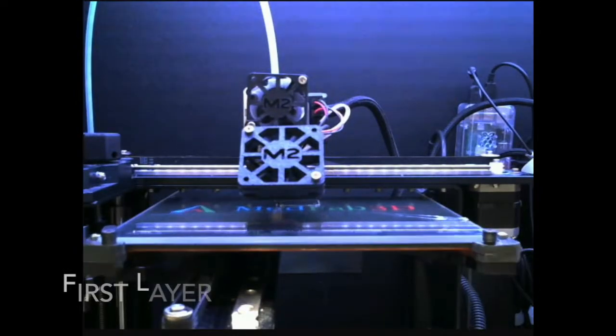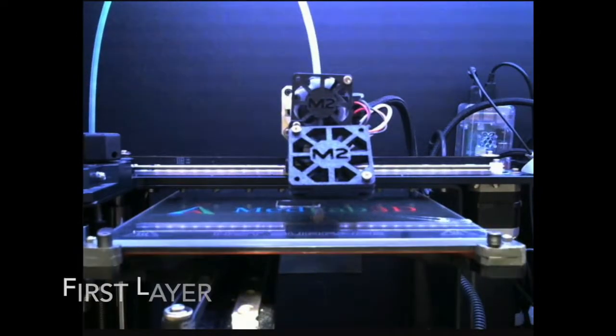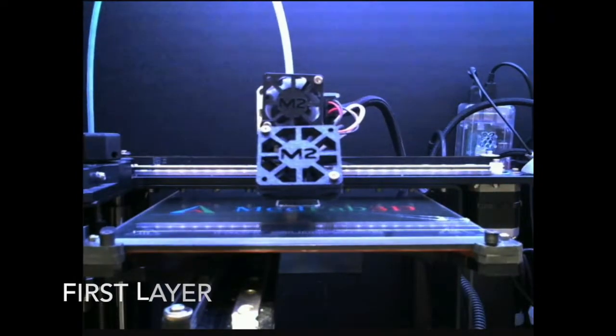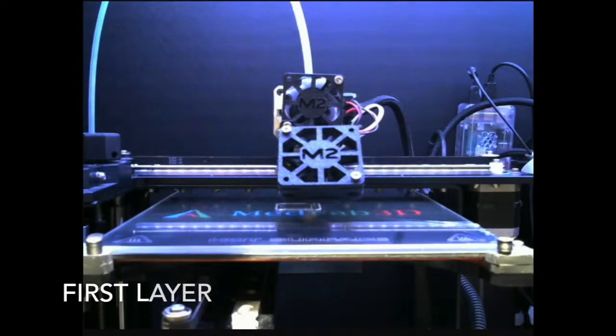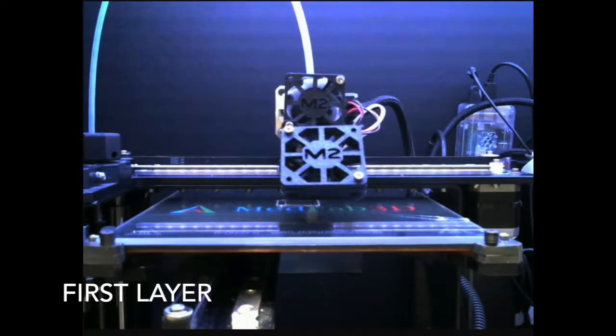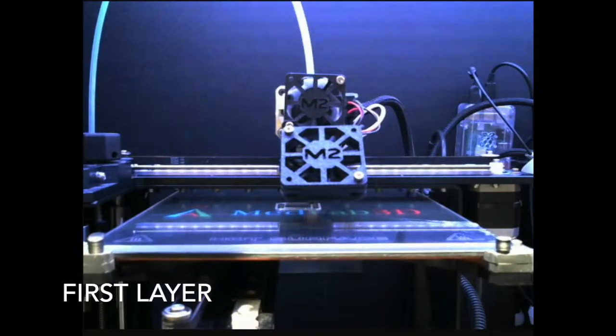And what it's doing is purging material through the nozzle, stabilizing the plastic flow onto the bed, so that when it goes to print the first layer of the part, we have a steady, consistent plastic flow and the part is fully printed.